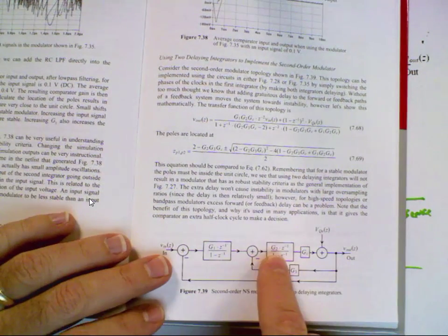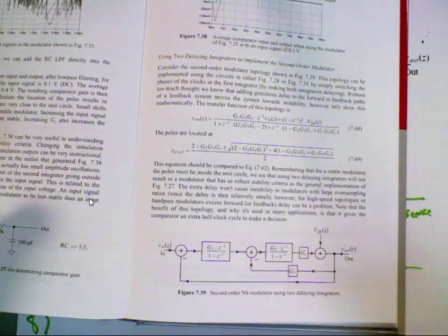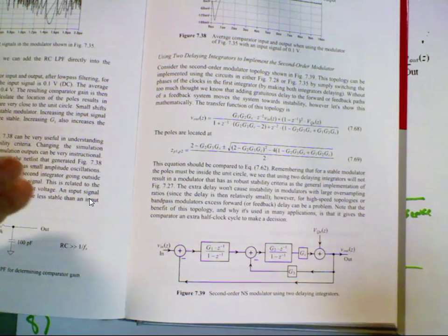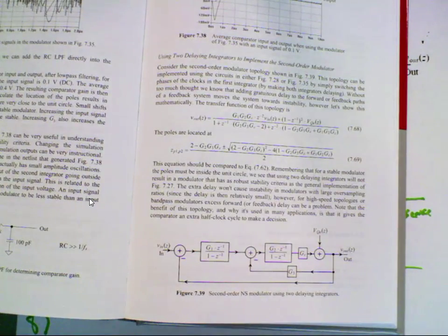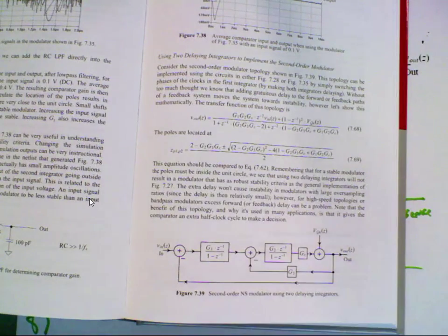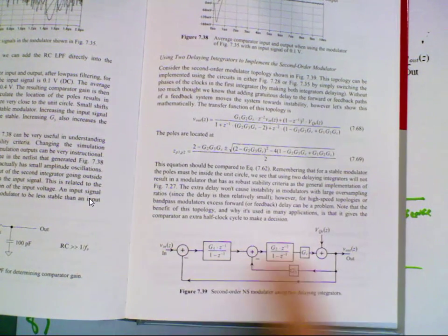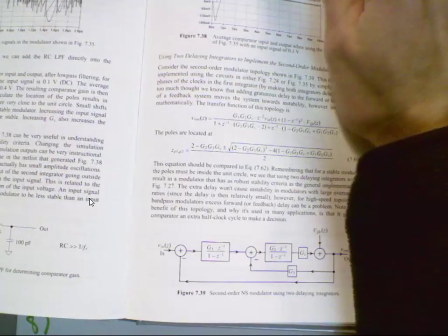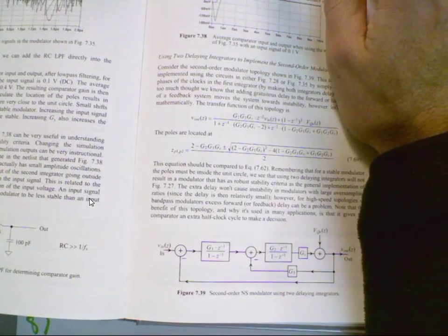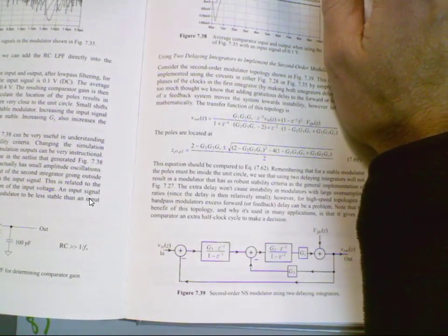If you have more delay in your forward path, it's going to be more unstable, right? I mean, it's like me saying I'm going to drive my car, but instead of looking at the road, which is the forward path, I'm going to look at the road after a 1 second delay. Well, if it's a 2 second, 3 second, the more delay I have in looking at the road, the more unstable I'm going to be driving my car, right? It's the same thing. If I had more delay in my forward path, then I'm going to have more chance for instability. So don't think of the math, all right? Does that make sense to everybody? More delay, more likely unstable.